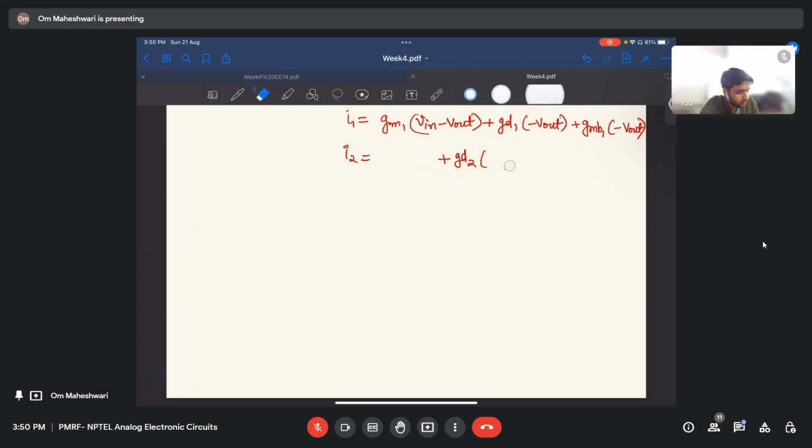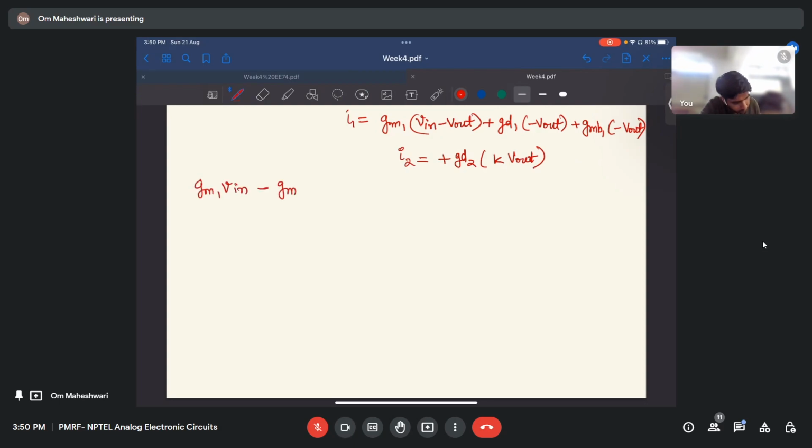And I did Vx as kV out. Okay. So GM1 V in minus GD1 V out minus GMB1 V out equals GD2 K V out.